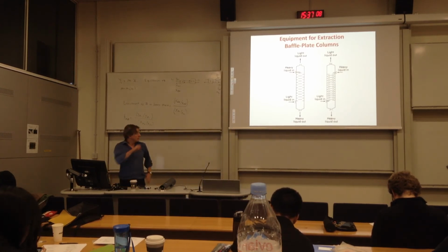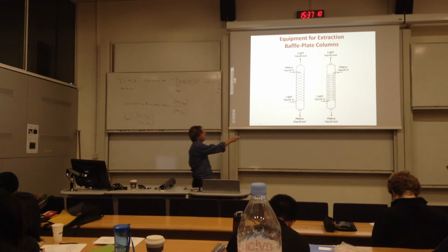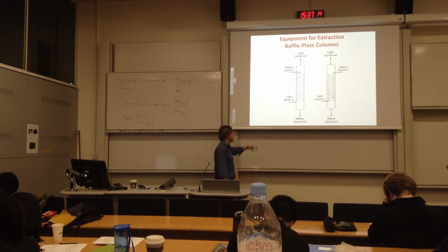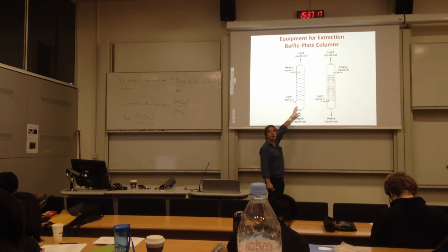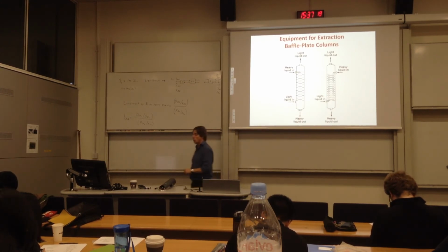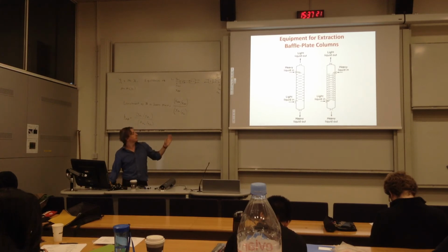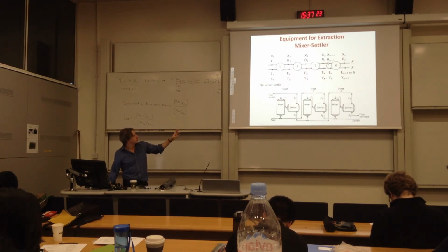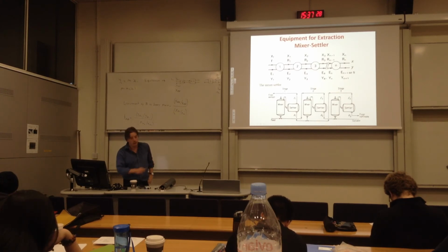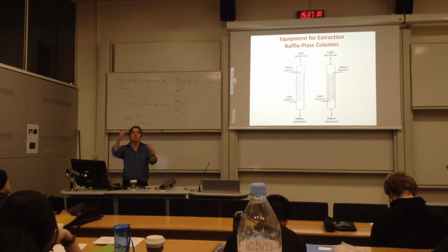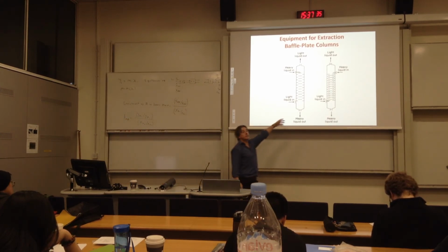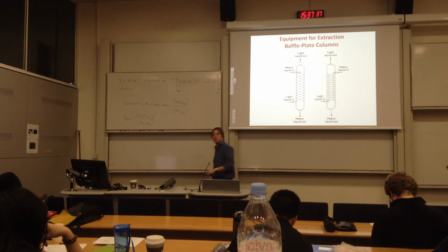And the number of stages is typically something that you can calculate here. So, for example, a certain distance on the column acts as one stage where an equilibrium is reached, right? So it's not as obvious as in this case, where each of these is one stage, stage 1, stage 2, stage 3. Here in a column you can have, in the same equipment, the same column, 5, 6, 7 stages, 15 stages, whatever, depending on the design of the column, right?